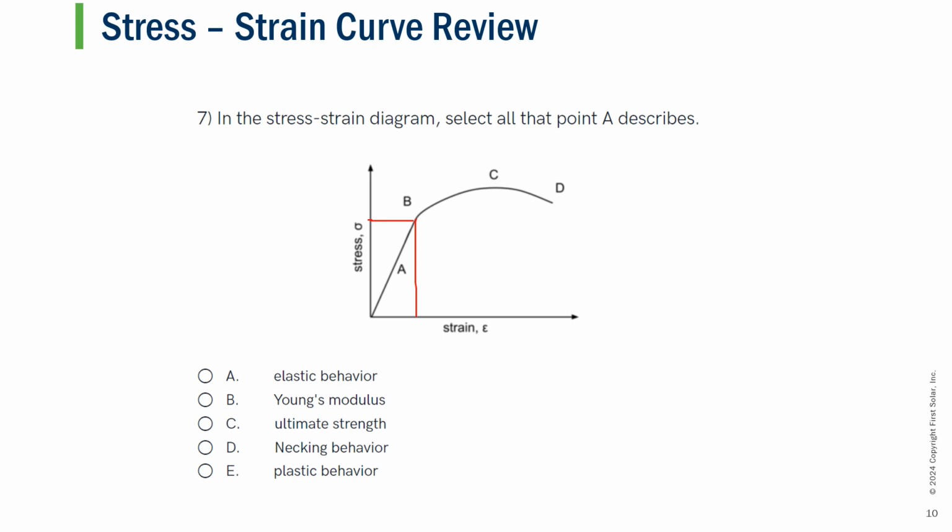So we know that the linear part of the stress strain diagram, essentially right off the bat, refers to Young's modulus. And what Young's modulus tells us is that you can stress or strain a member from this point to, say, this point, and then removing this stress induced to it, the deformation will go from whatever value you had back down to 0 and not experience any plastic deformation.